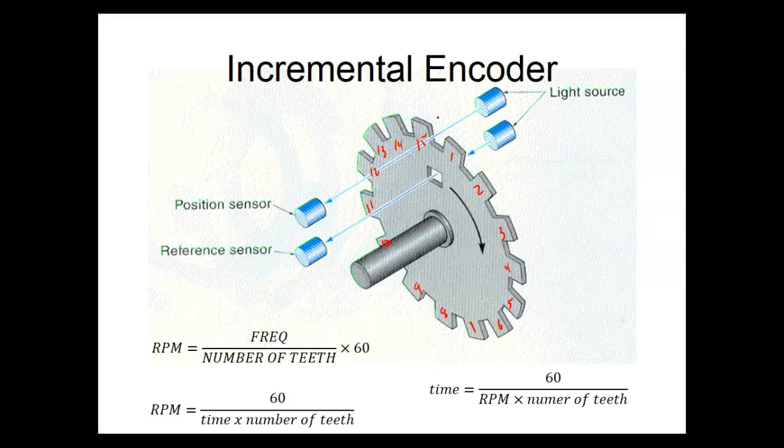Okay. So what would happen on my sensor here, which is probably a through the beam sensor, right? What would happen on there is that for every 15 pulses, 15 pulses is going to equal 1 revolution, right? Everybody okay? This makes sense.